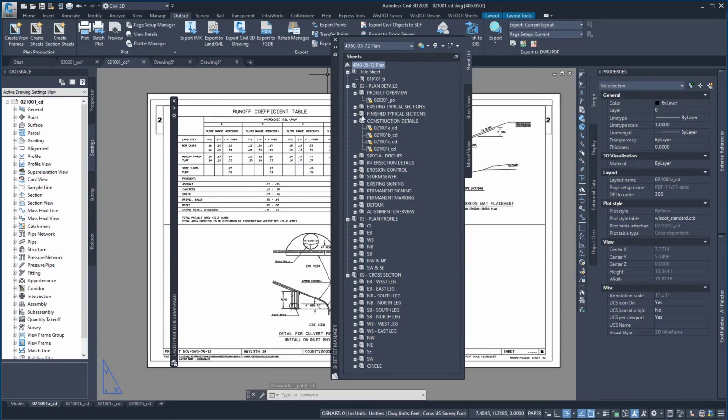Another thing, as I mentioned before, there's also another driver that WisDOT supports called the DWF. And that's Autodesk's native format or driver that's comparable to PDF. It's their version of PDF basically, but it's built specifically for Autodesk products, so it's going to have a much closer integration with the output that you're going to get when you plot. You don't always need to use the DWF, but it comes in handy if you're having issues, say with fonts not coming out or some imagery that's not plotting correctly. So that is another option to do that.